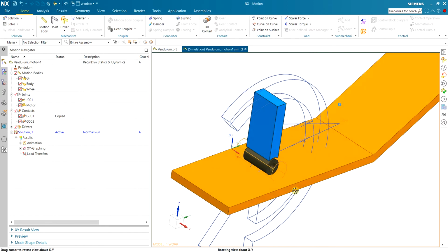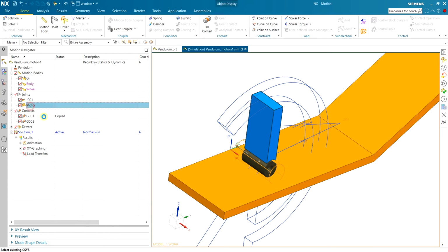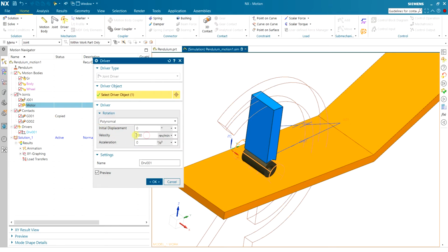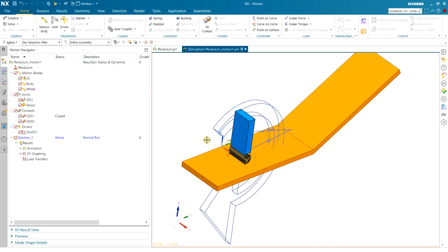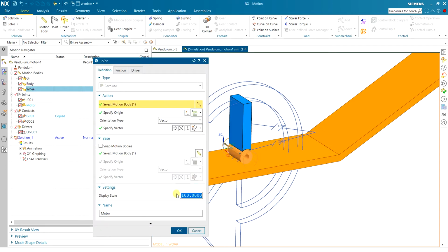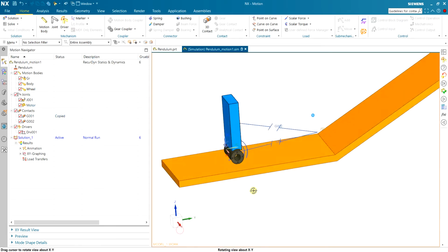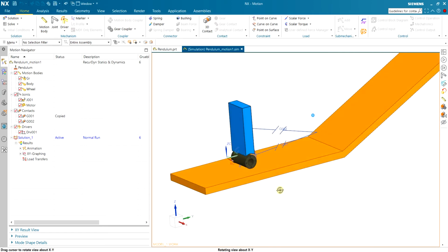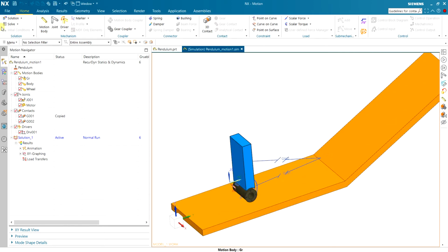Of course, there is no difference. I could just use negative velocity here. Under the velocity, I could use a negative 100 RPM, and it would do what I like. But it's better this way. It keeps everything more simple. And I can bring down the scale a little bit. So now it's going to turn with 100 rounds per minute. Let's run the simulation and see the result.